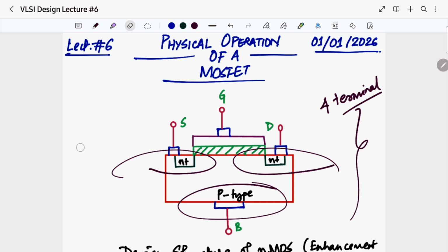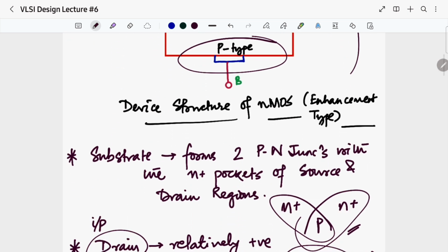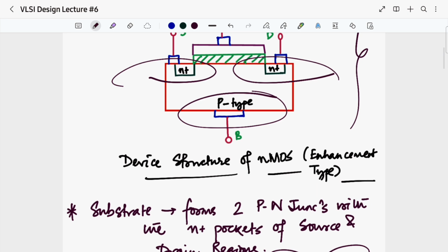Okay, so never get confused. You're studying that it's a 4-terminal device, but when you go into the lab of analog electronics and you see that the MOSFET has 3 pins, you might get confused. So this is how we are getting that 3-terminal behavior of a MOSFET, but in actuality a MOSFET is always a 4-terminal device. This question is likely to become a part of your viva, and most of the students of 6th sem might get confused.